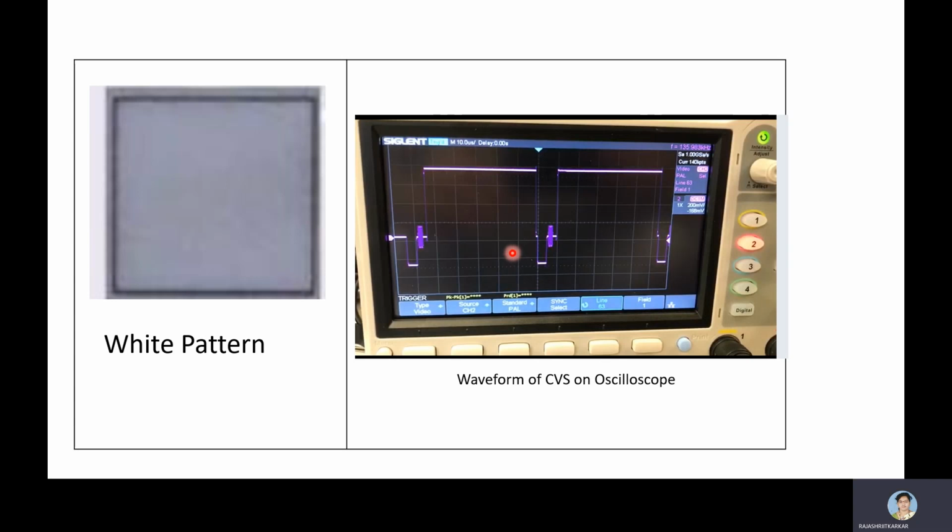This is the total white pattern, right? So total white will be on the top. That is 75% will be total white, and we'll say 12% is the black level. Between 10 to 12% there is no information transmitted, because it is a brighter than bright level, and hence in that level we do not transmit any signals itself, right? So this is what you show, that is white.